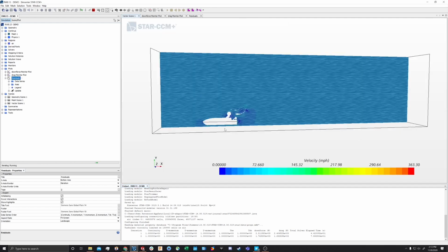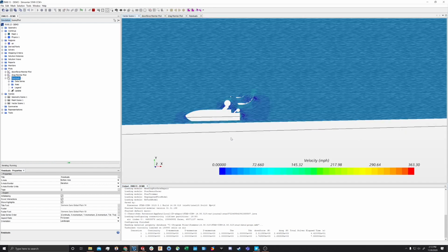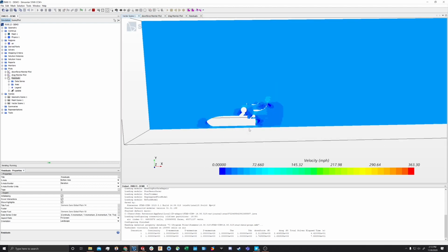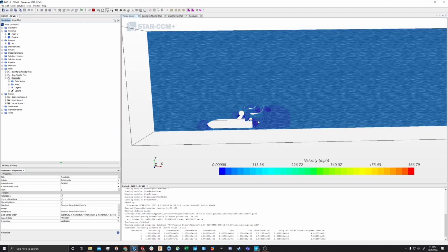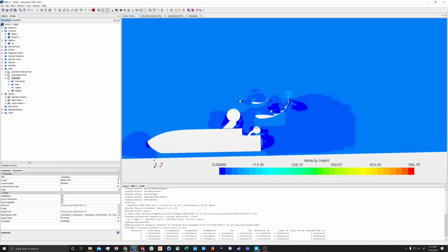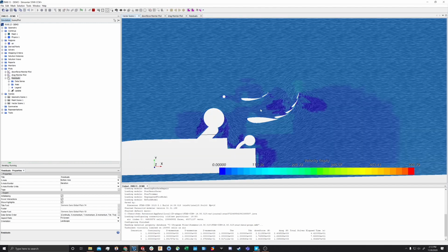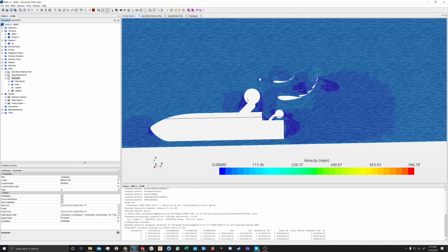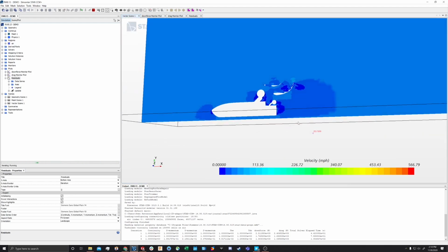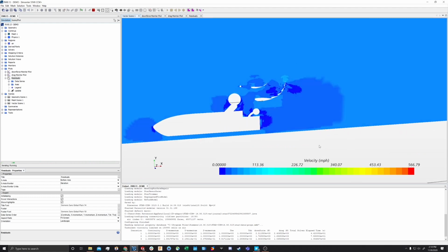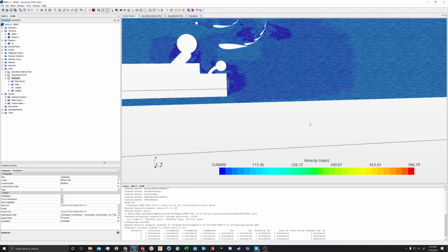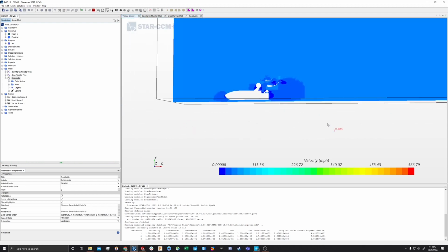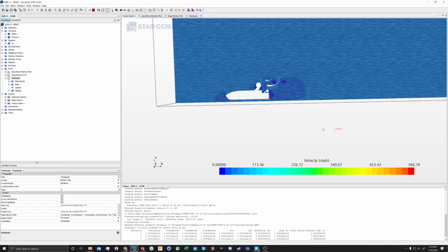We're actually going to switch over here and check out the vector scene. Again, it's kind of messed up right now. This will happen. Your first few iterations will be a little messy. Usually it takes maybe 100 to get to a sim that doesn't have any weirdness going on. And we usually run these for 1,000 to 5,000 iterations, depending on how important the given sim is.